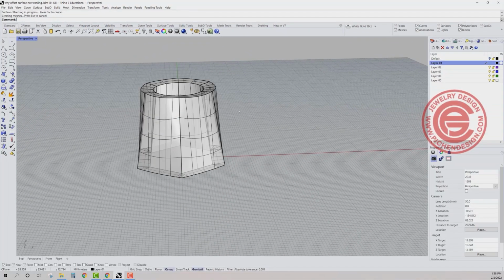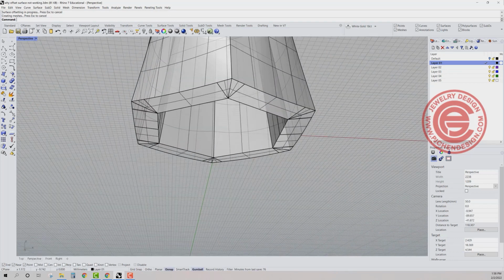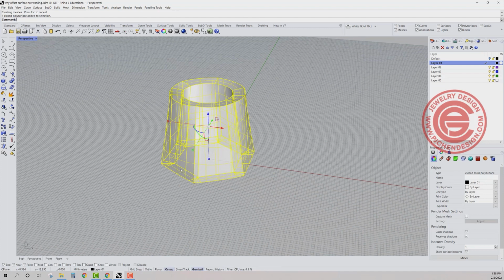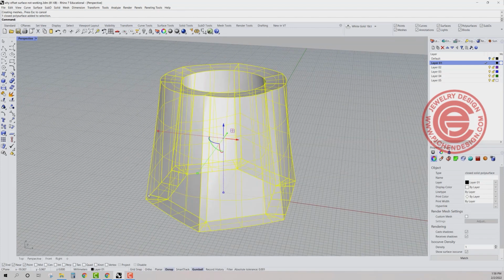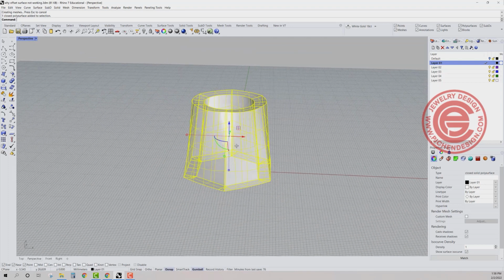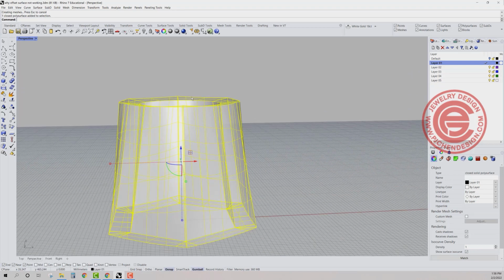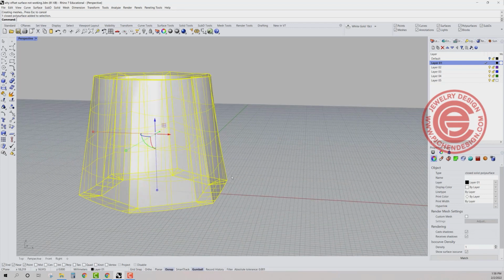So let's click on this one. Okay, it looks better, we have sharp edges right there, and we want to make sure this one is a closed solid polished surface. Because that sharp corner is going to change, it breaks when you have something round coming into the point, right? Another thing you will probably notice is that the top seems not flat, right? When you offset, that's not something you wanted, because you want sharp edges, and you also want it to be flat.